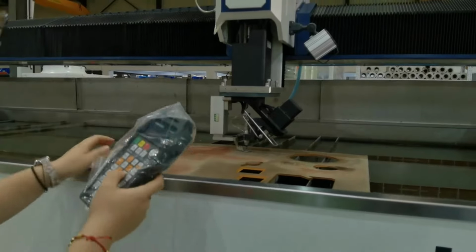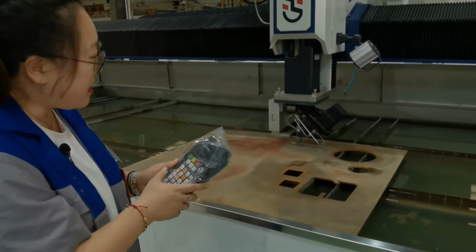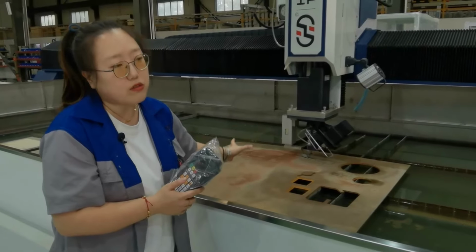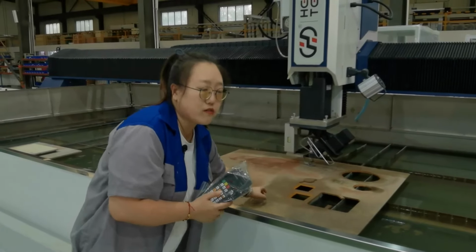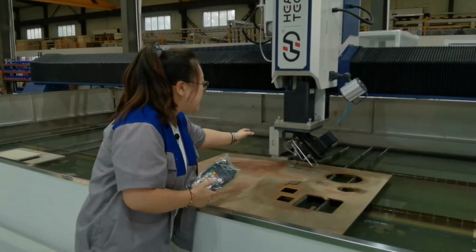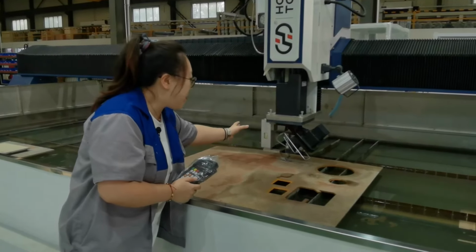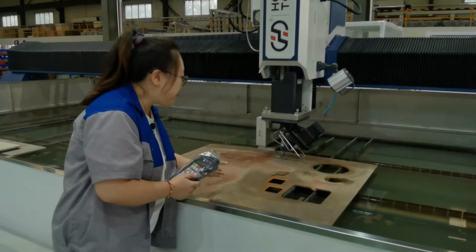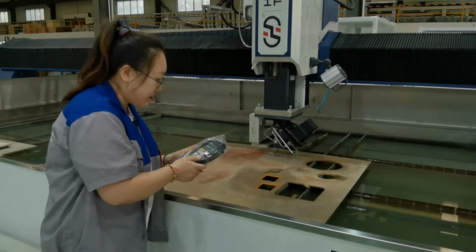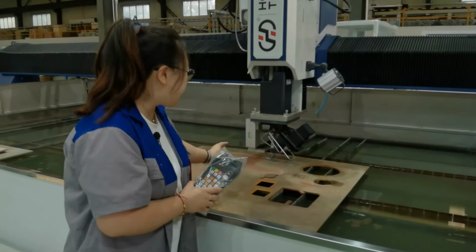Like this one is the lowest part you need to set the cutting head. And we have set the limit too, and it also can guarantee your nozzle can't touch the materials when you cut. And in your machine there is the auto height following system. It will guarantee your nozzle won't be broken when you cut different height materials. So now this is our cutting 0 point we have set.